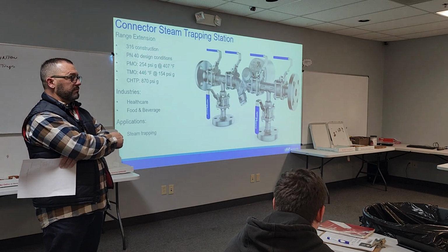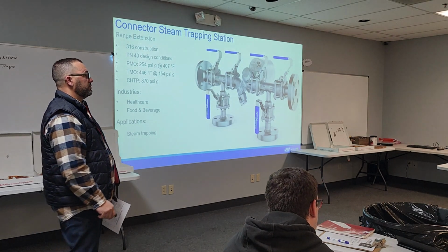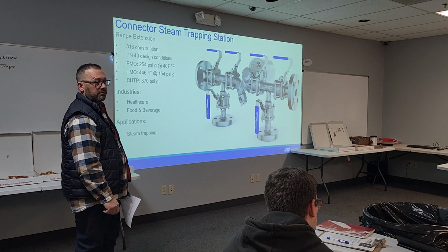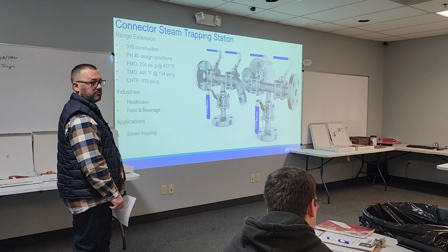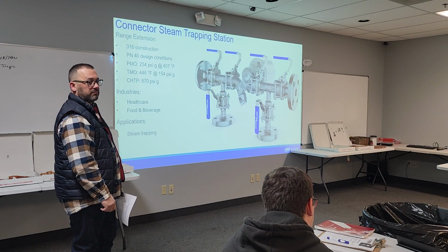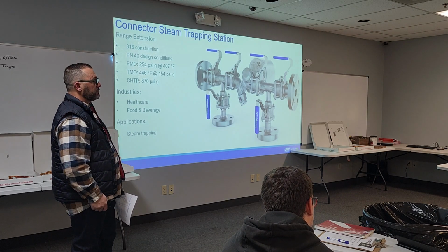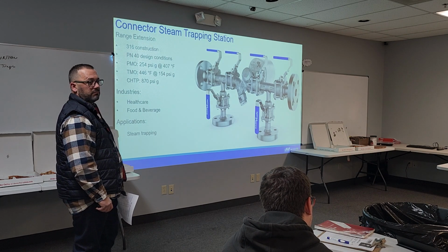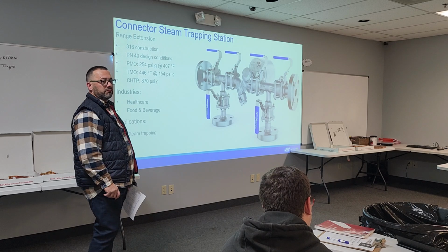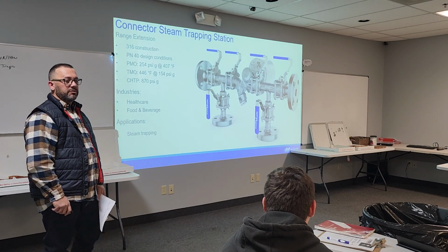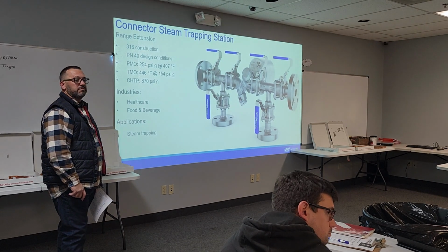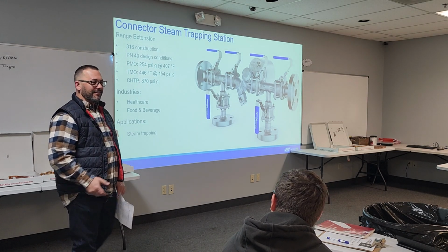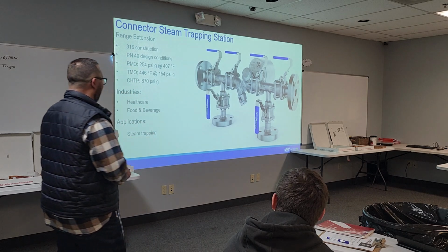Do it on Christmas Day, yeah. How would you have multiple valves on both sides, on the discharge side, on the condensate side? You're saying somewhere downstream there needs to be at least two valves? It's built-in safety, is what it is. I understand what it is, but you're telling me that there's going to be multiple valves on the condensate discharge side, the downstream side? If there's not, we're not going to do it live. That's what I'm saying. The system needs to be shut down. Because look, there's a lot of live steam and condensate. It only takes one.